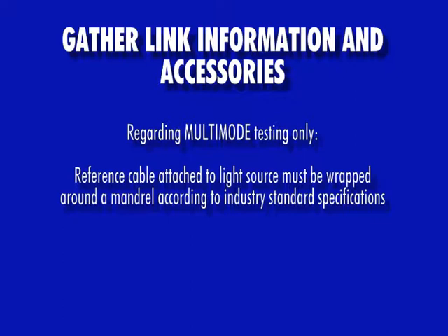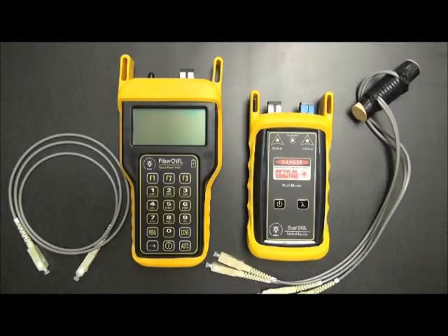Finally, if testing multimode fiber, the launch cable attached to the light source will also need to be wrapped around a mandrel according to cabling standard specifications. Refer to OWL's video on mandrels for more information.